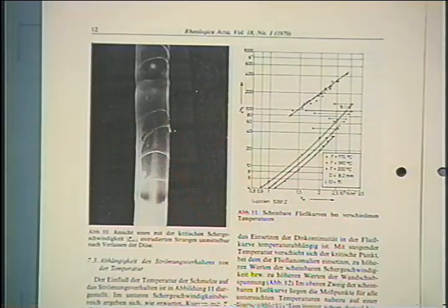Let me go into Ulan's paper. I think he has a picture somewhere. The extrudate looks fairly nice. Here, this is the extrudate. It's not distorted very much, and the surface is not perfect, but it's okay. And indeed, that's the operating condition which is used for producing the one-gallon milk bottle.